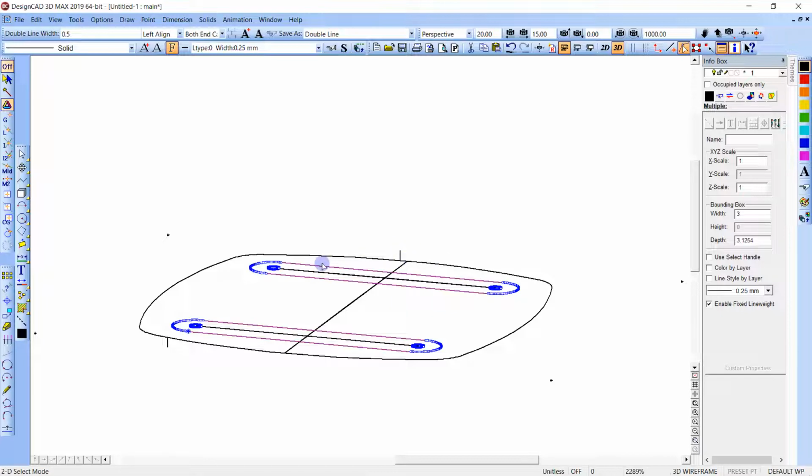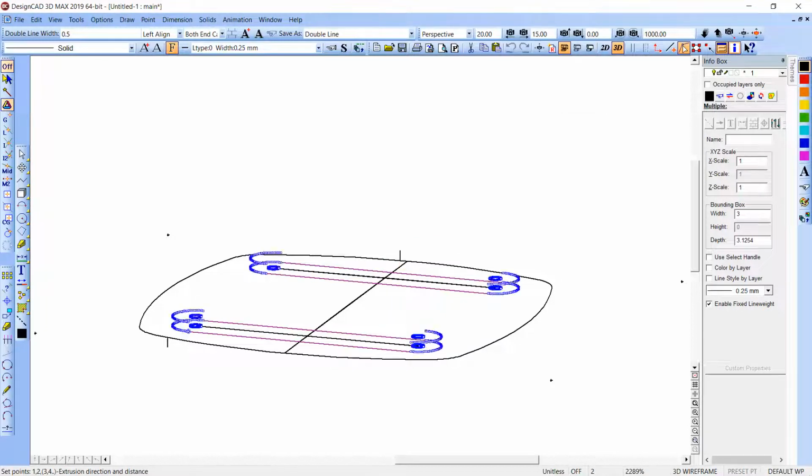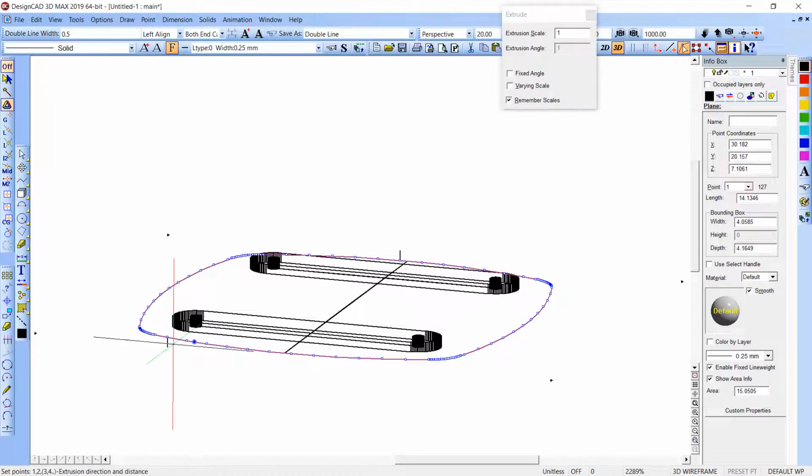And then I'm going to extrude that. Nice thing, I can draw while those are highlighted. It doesn't unhighlight them. Just hit X and extrude to those 2 points, enter. And then the big one, X, and then just right click there and there, enter.